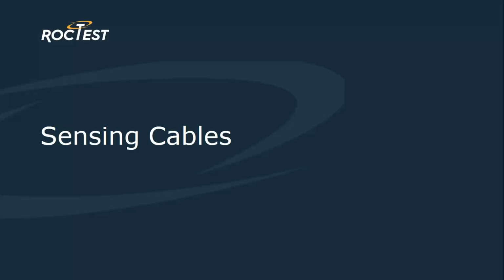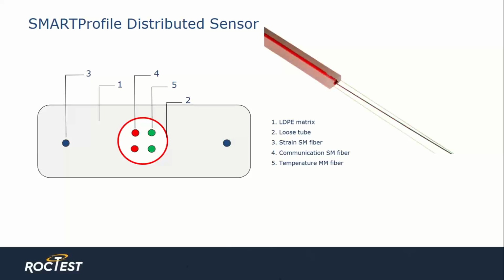So let's see now the sensing cables family. The first one is the SMARTProfile, which is a combined strain and temperature sensor. The sensor has two fibers for strain, the blue ones, two fibers for the data communication, the green one, and two fibers for temperature sensing. The fibers are encapsulated in a polyethylene profile, as you can see here.